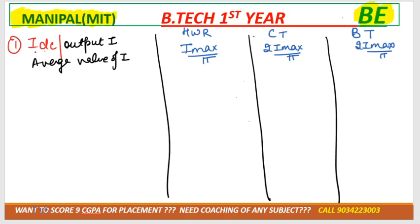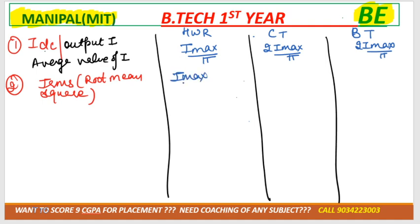Okay, clear? Now in the second case, if they ask you to calculate IRMS, IRMS is the root mean square. You studied it in 12th, right, root mean square. So for this particular case, that would be I max by 2 for half wave rectifier, I max by root 2 for center tap, and I max by root 2 for the bridge type.